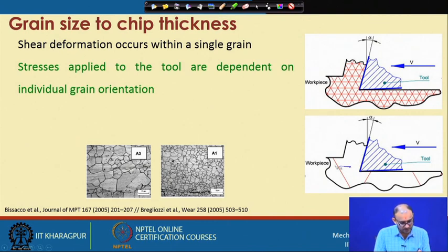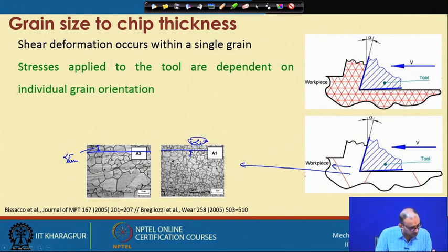if you use this particular process here, let us consider your depth of cut is very small. So whatever is 25 micron, let us cut this 25 micron, and same way here, this is also 25 micron, and we are using a micro machining operation for cutting this particular material. Now coming to this part, first this one. So even if you are cutting at a 25 micron depth of cut, still you have a high probability of getting the grain boundary, because the size of the grain is even smaller than what we have seen.